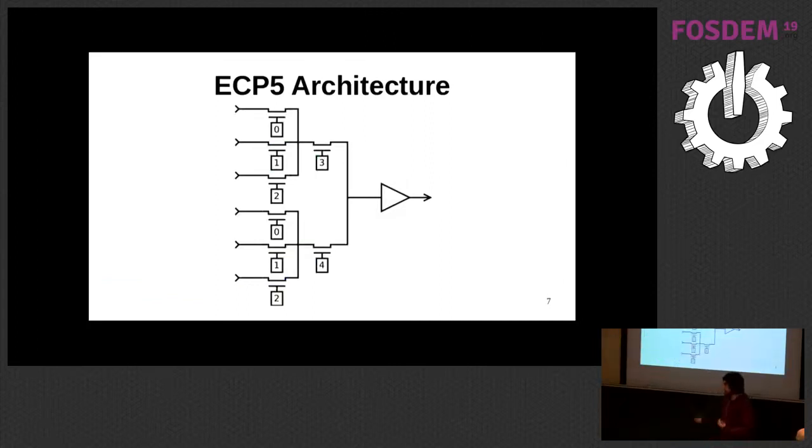So I mentioned that it's a unidirectional architecture made up of multiplexers. Once you've looked at the bitstream, you can actually start to get an idea what the circuits on the silicon would look like. So this is basically what programmable interconnect in an FPGA looks like. These 0, 1, 2, 3, 4 are bits in the bitstream. These select one of these 6 signals coming in to a signal going out. So for example, that would connect to the input of a logic function, and these would be your general routing throughout the device. And you always have this cascade of 2 multiplexers, which works out to be quite an efficient way of doing this in the silicon.